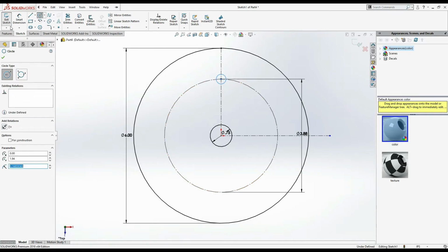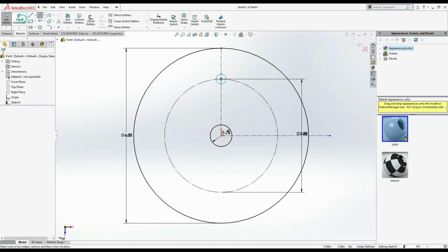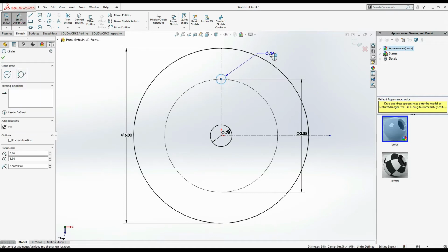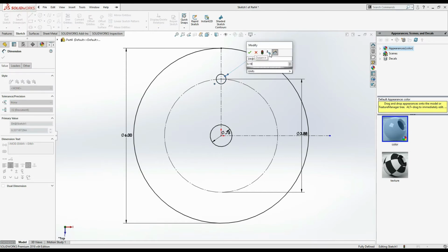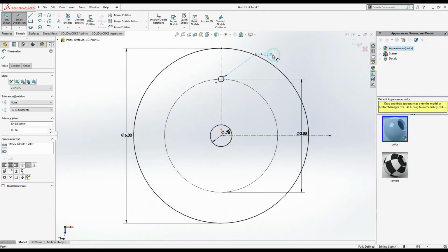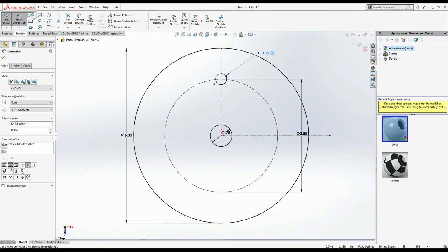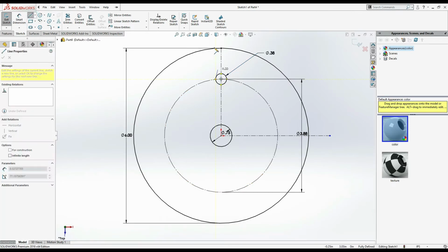This is the distance, and you can find its value as 0.19. It is a 0.19 radius, so make it a diameter of 0.19 by 2. Now select line from its edge to end chain. Now again from here to touch this line, press escape.